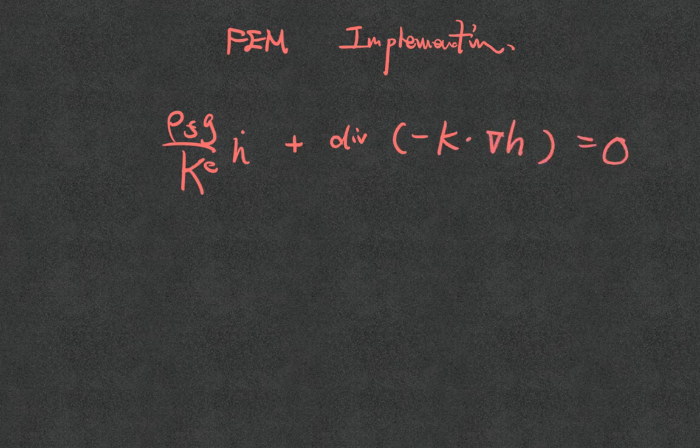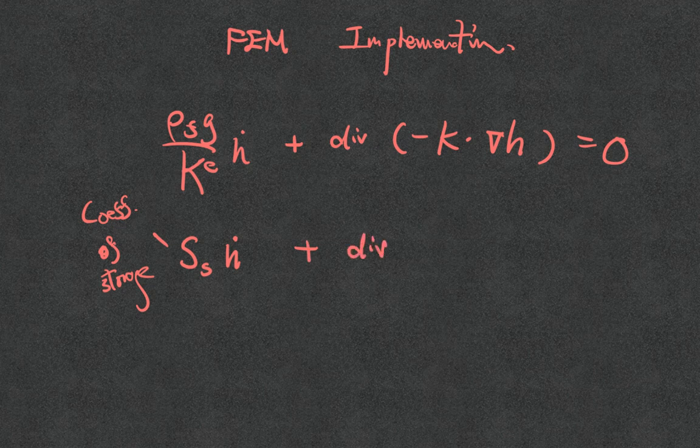Okay, so remember these equations. Ke is the bulk modulus. I will assume this is a constant. Rho F, I will assume is incompressible, so it's also a constant. G, I would also assume is constant. So in order to not keep writing this term, I will simply write it as this. SS is the coefficient of storage. You just add a new notation there. No new notation, not terminology. And then I would actually have this term: one equation, one unknown.